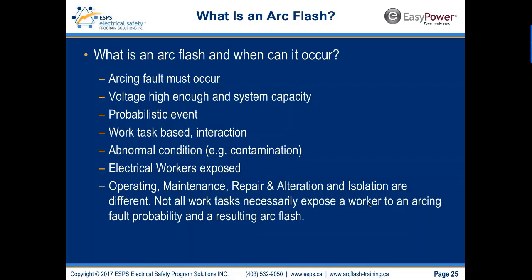All right, so again, electrical workers are exposed to arc flash. Non-electrical workers should not be exposed to arc flash due to their work tasks, or again, the equipment not being in a normal operating condition. So through maintenance, we maintain energized electrical equipment in a normal operating condition, and we can have people operate it, stand in front of it, be there, and they don't need arc flash and shock clothing on. And I'll discuss operating, maintenance, repair, alteration and isolation in a slide coming up.